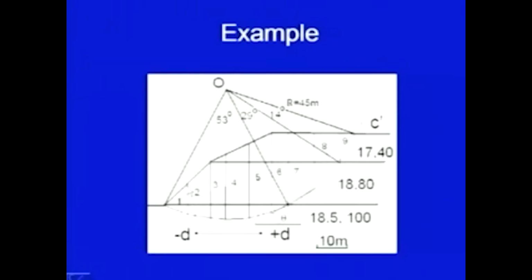So, simply you have to find out this area. Let us say area A1, area A2, then A1 into 1 into its unit weight plus A2 into 1 into its unit weight. That will give you the weight of this slice.